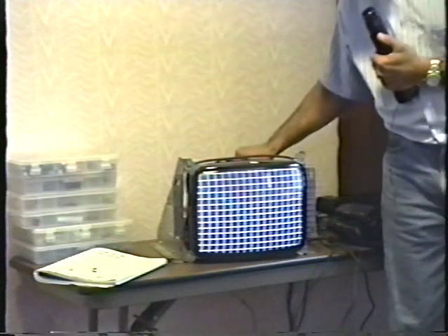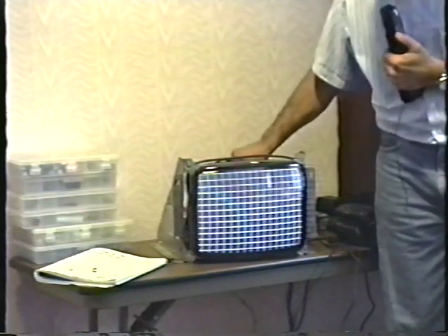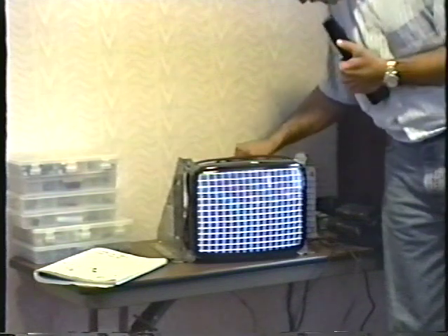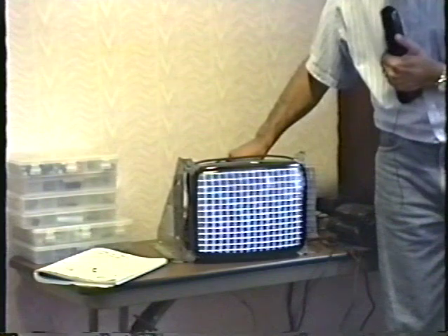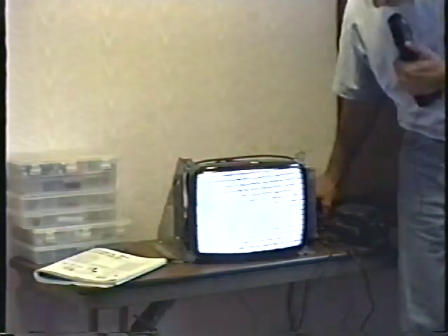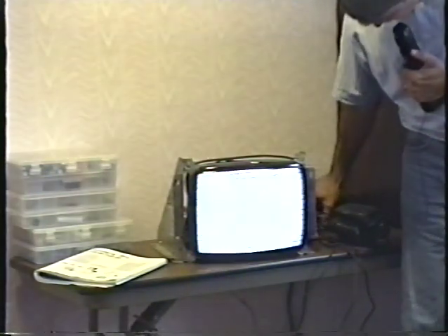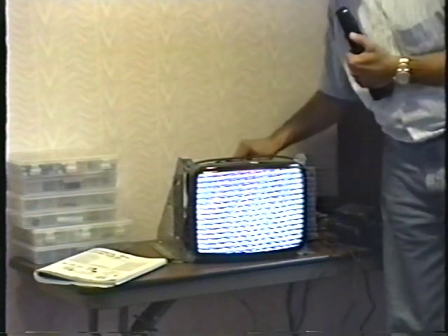Horizontal sync is just the opposite. When you have a problem with horizontal sync, the picture will shift left and right. It's actually difficult for me to really show this to you right now, but loss of horizontal sync can look like this, depending on the pattern I have on the screen. There's the color bars. If you try to adjust the horizontal hold, if you can't get it to lock in place, you have a horizontal sync problem.